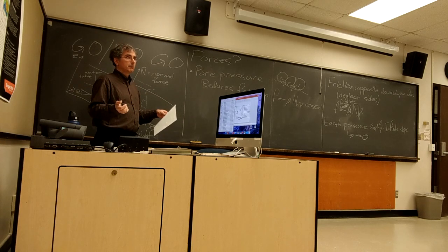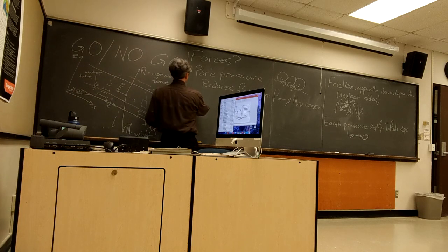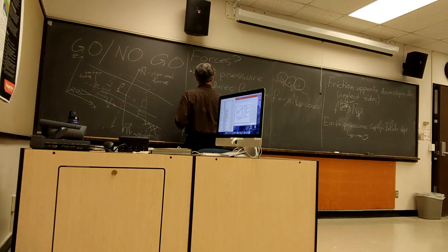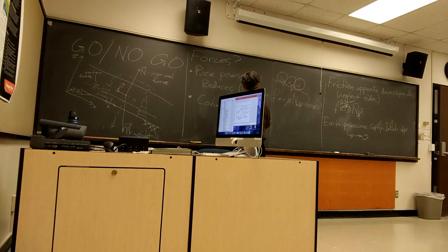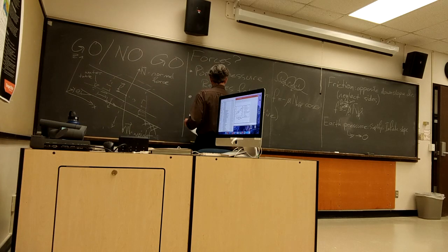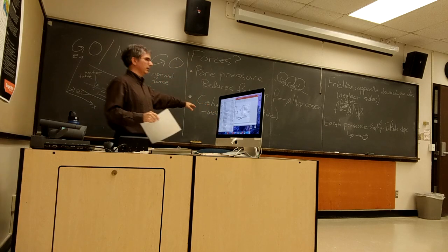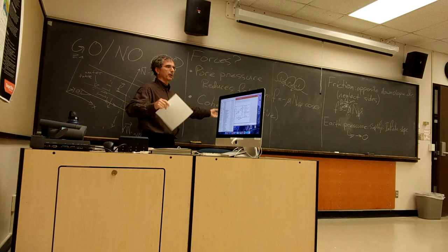What's holding it up? Trees. Trees, but specifically their roots, right? And there could be other things too. So cohesion is what we're after. And let me put that we're really after an effective cohesion, because we want both the molecular cohesion due to the van der Waals forces between clay grains or particles, right?